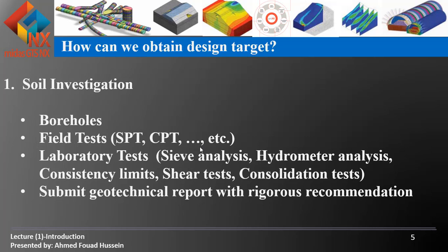With boreholes. We have to go to the site and make boreholes and take samples so we can start to study the stratification and the lithology of the soil in this area. So we know where the sand is, where the clay soil is, where the silt soil is, and where the gravel soil is, and whether this site has a weak soil or strong soil, or whether it has a bedrock or not. So all these questions are related to lithology, because the first